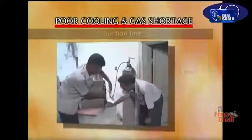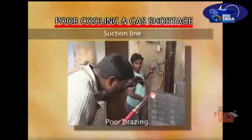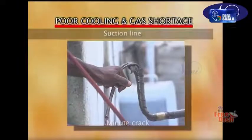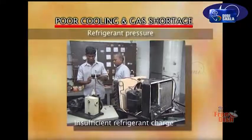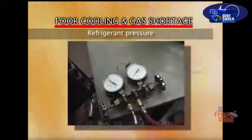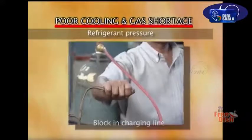Check the suction line. There could be a minute leak in the suction line. This could be due to poor brazing, and there could be a minute crack in the suction line. Check refrigerant pressure. There could be insufficient refrigerant charge, or there could be an error in the gauge or a block in the charging line.